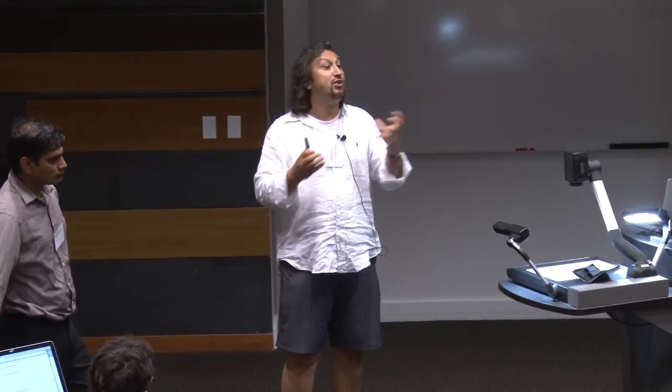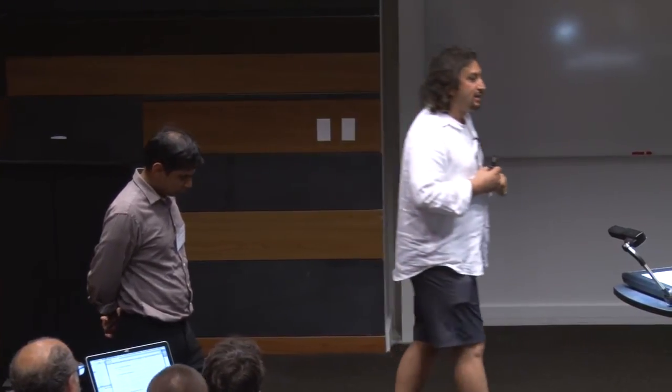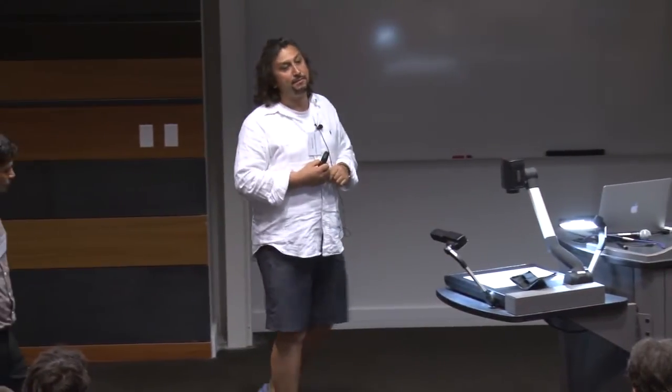When you get smaller, the stability issues change because inertial forces are much less. I just wanted to remark that cockroaches also go bipedal when they go fast enough. They go from the alternating type to bipedal. Even if you look at this robot, in the trotting gait, it's basically like a biped in practice, is that right? With a trotting gait at very high speeds, it's almost, in some sense, like a biped. The idea is you want to maximize your flight phase rather than ground contact phase, and that's why multi-leg systems, even at small scale, at some point move more into flight mode, and multiple legs become redundant.